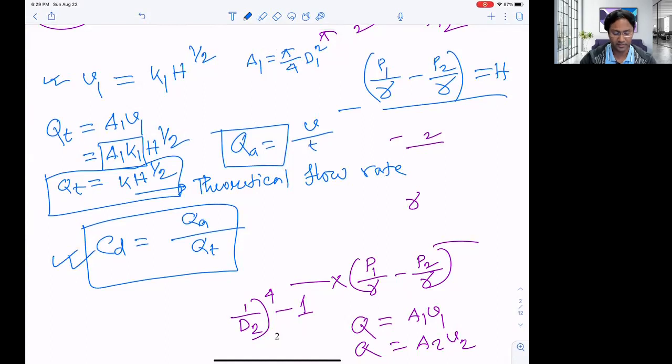Once we have that, we know that this efficiency should be 0.99 for a larger flow measuring device or Venturimeter, and for a smaller one, this should be 0.98. That means 98% and 99% should be the efficiency. Then we can use this flow measuring device for practical purposes. This device is useful not only to measure incompressible fluid like water, but also compressible fluid such as gas and other fluids as well. But the only disadvantage of this device is the head loss.